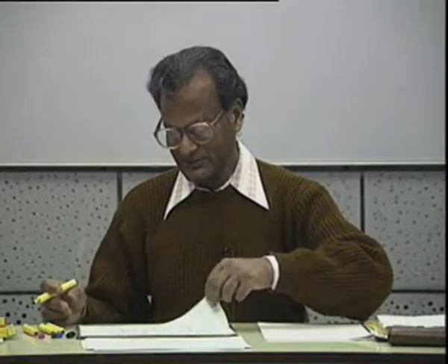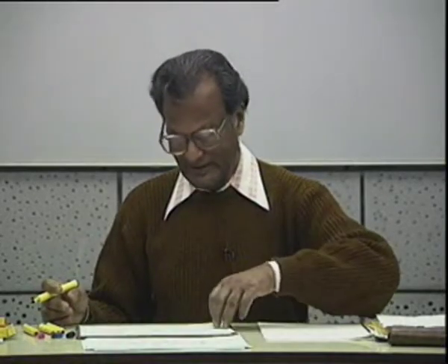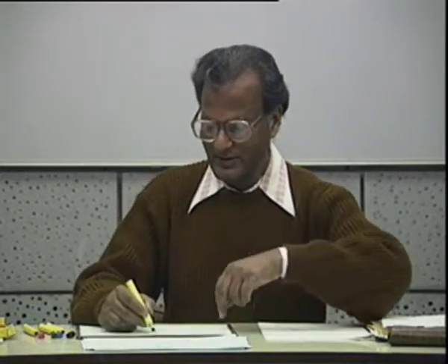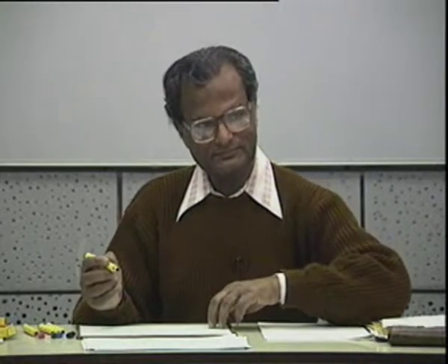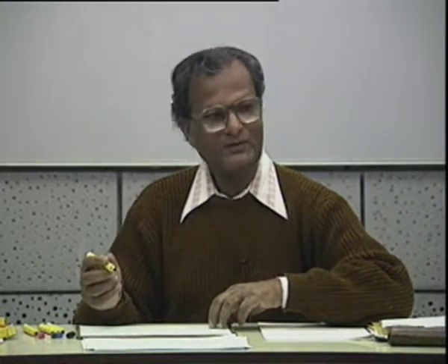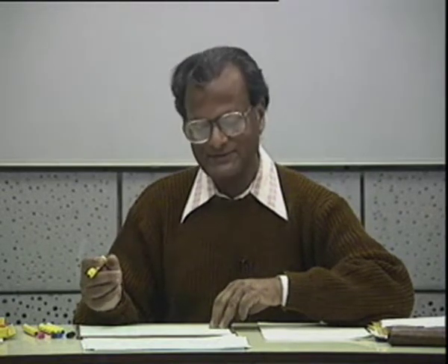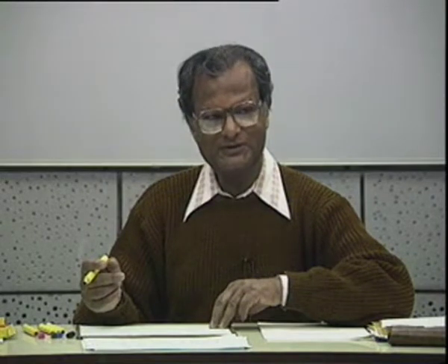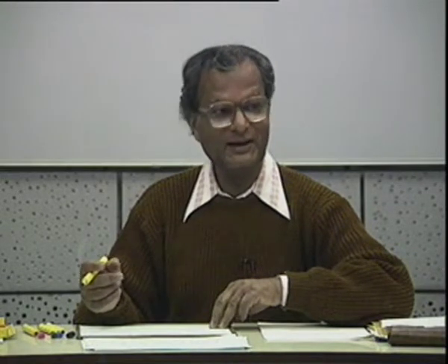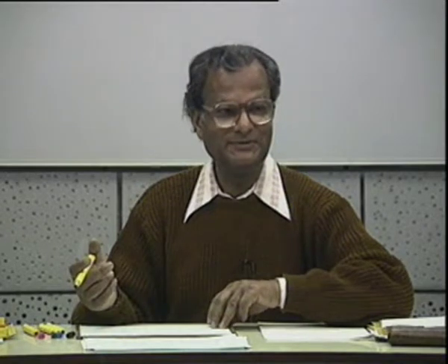Now, let's go to the common mode gain. In the DC analysis, we considered the output as the differential output, and here we are considering it as the unbalanced output. We also split the voltage. The voltage was VD by 2 and the output was VO by 2. So it's a factor of 2 which divides both numerator and denominator, and the gain still remains the same.